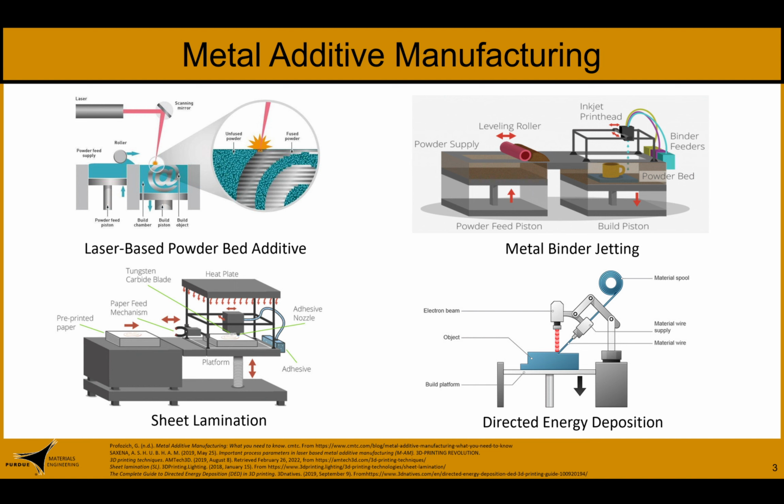This technique jets powder onto the build platform to print objects, similar to a 2D inkjet printer. A liquid binder is applied to combine the powder layer by layer to build the desired object. Printed parts are initially fragile and require post-processing, sintering and infiltration, to be strengthened.